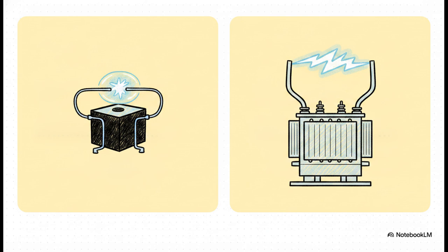Now, what's really fascinating is how engineers actually tame this wild voltage kickback out in the real world. The danger is constant arcing, which destroys delicate relay switches or, even worse, blows out incredibly expensive transformer bushings. So the solution? We give that collapsing magnetic energy a safe place to go. On smaller circuits, you'll see flyback diodes or snubber circuits wired right across the coil to gently dissipate the spike.